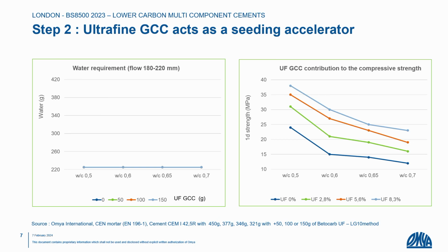Another comment, you see the curve of the control. This information is interesting. We will see after some example with CM1 and CM3. We have here a first information about the water sensibility of the binder, of the cement in this case. That is to say, we can use this model formulation to evaluate the performance of a cement alone, a combination of two cement, or a cement with one or different mineral additions. And we will not only consider the compressive strength, but we will be able also to consider the water sensibility of the combination.